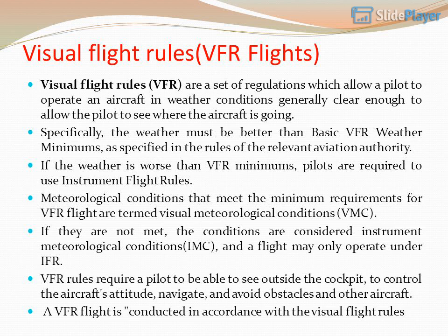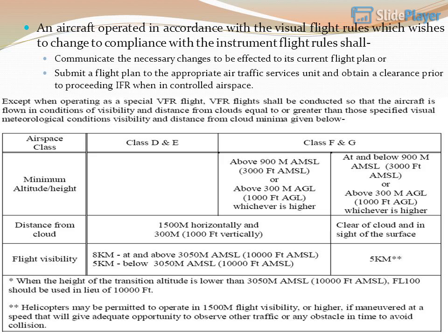A VFR flight is conducted in accordance with the visual flight rules. An aircraft operated in accordance with the visual flight rules which wishes to change to compliance with the instrument flight rules shall communicate the necessary changes to be effected to its current flight plan or submit a flight plan to the appropriate air traffic services unit and obtain a clearance prior to proceeding IFR when in controlled airspace.